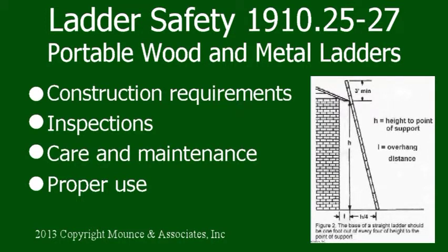Check the ropes, check for any dents, and make sure the feet of the ladder are not worn or damaged in any way. If ladders are exposed to any oil or grease, make sure it is removed before using. Any ladders having defects should be taken out of service immediately, not used again until repaired.